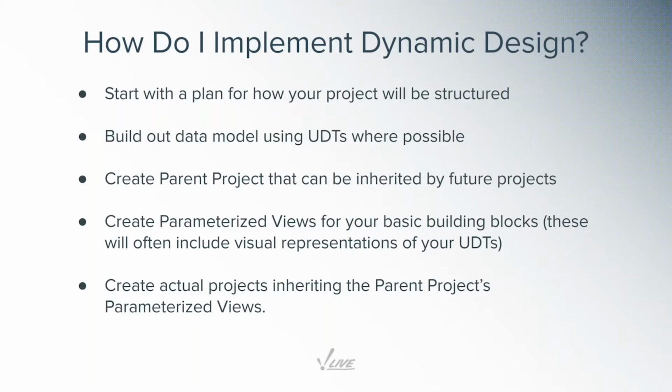Often your parameterized views will match your UDTs: if you have a motor UDT, you're going to have a motor parameterized view, or if you have a device UDT, like you'll see I have, it would match to a device parameterized view, and so on. Then after you've created all of these parameterized views inside a parent project, you go and create the actual projects inheriting all of those parameterized views.